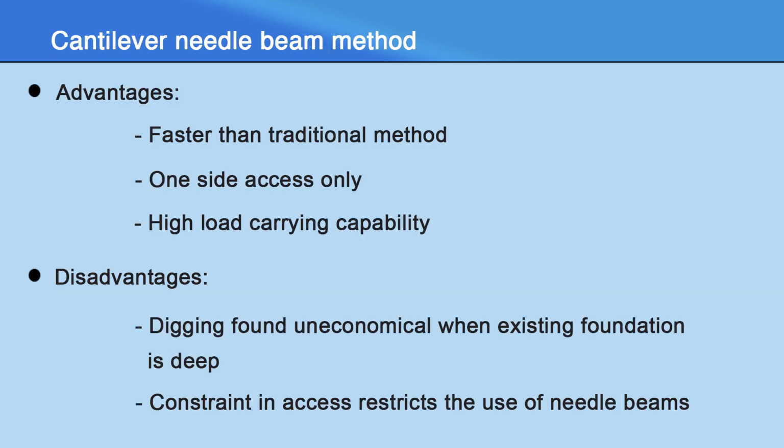Advantages: first, faster than the traditional method, one side access only, high load carrying capacity. Disadvantages: digging the foundation is uneconomical when the existing foundation is deep, and there is a constraint in access restriction and the use of needle beams.